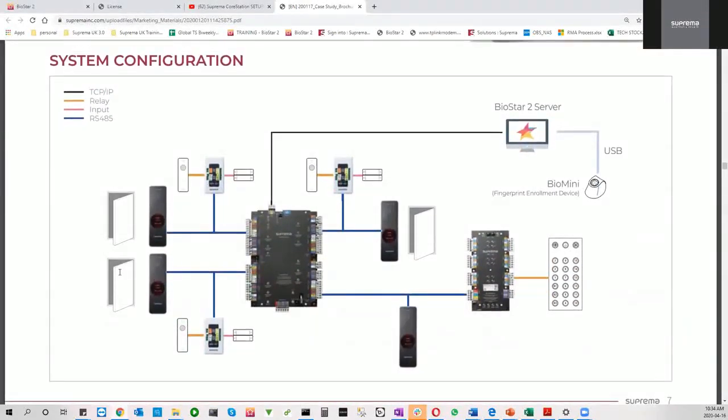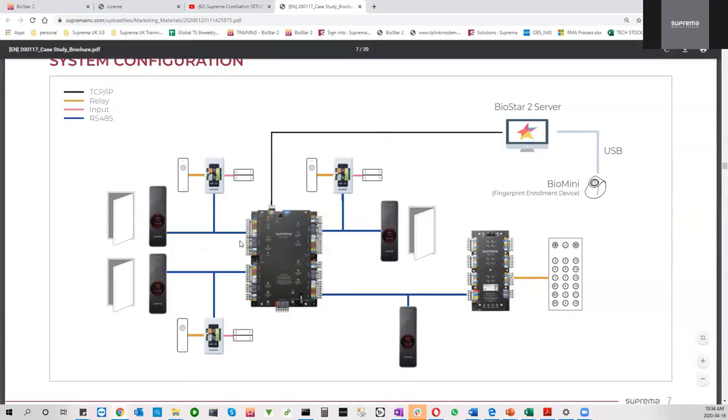All right, looking here. This is how they had it connected. You have the CoreStation as a centralized unit. Keep in mind right here, you have the RS-485, and you also have a door control in the CoreStation, but instead they have RS-485 going to the Secure IO, then daisy chain to the W2. What that means is you're not using the CoreStation to trigger that door or that lock. You're using the Secure IO. So it's very flexible in that aspect.